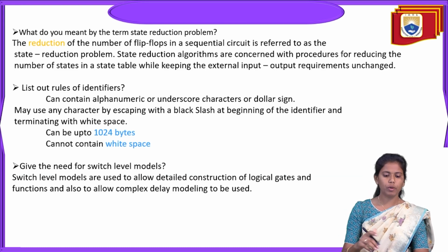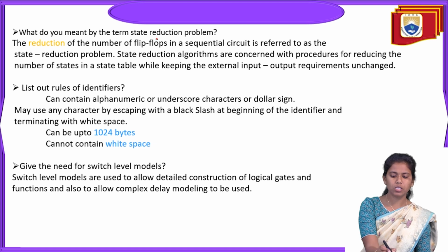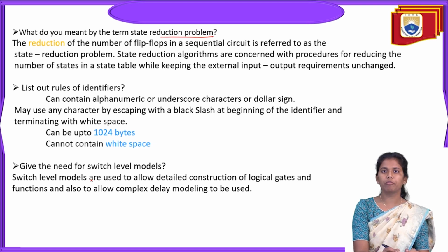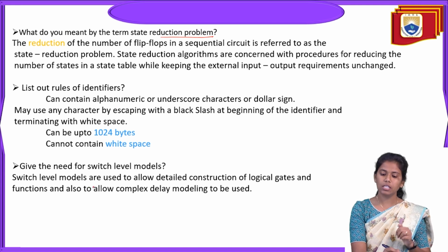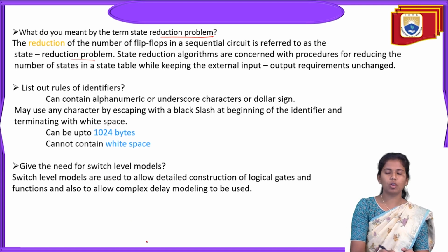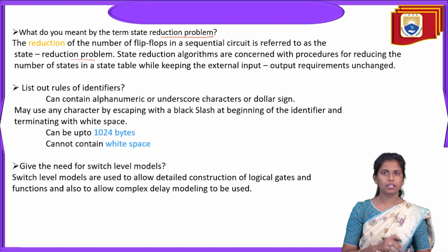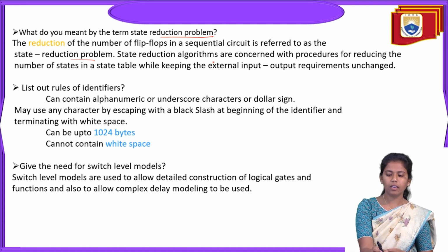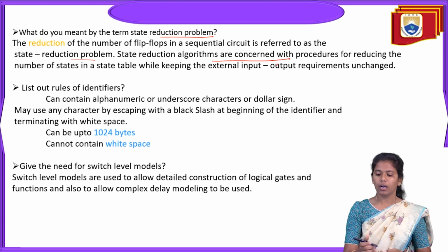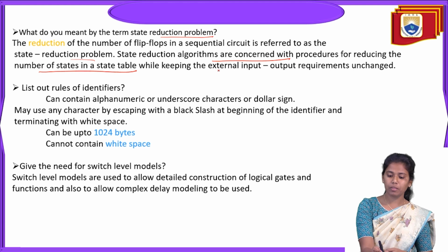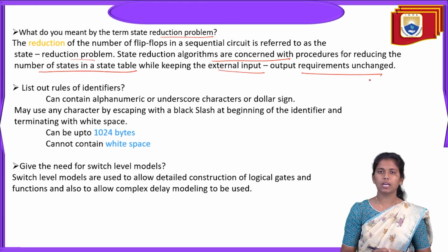Then coming to what we mean by the term state reduction problem. The state reduction problem is the reduction of the number of flip-flops in sequential circuits. So if the number of flip-flops is reduced in a particular state, then that is nothing but a state reduction problem, and the algorithms are concerned with procedures for reducing the number of states in a stable state while keeping the external input-output requirements unchanged.